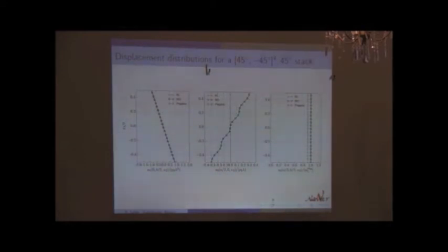Many plate theories introduce some zigzag functions to capture this effect. But it's just the fact that because of the different orientation of the layers, some components of the stiffness tensor are alternating, and you integrate them through the thickness, and you get those oscillations. That's nothing more. So this is an illustration for laminates.